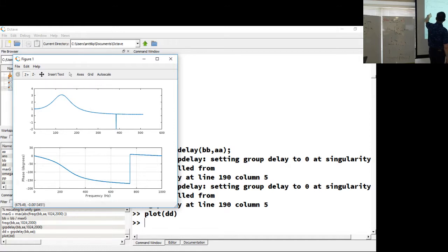That warning actually comes from the singularity, meaning divide by 0 at the notch. At the notch, you are exactly on that point. You cannot actually calculate the phase. There is no phase on a signal that does not exist.